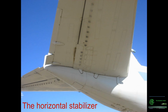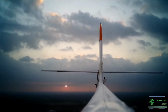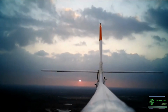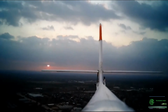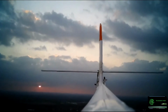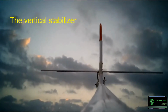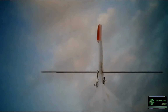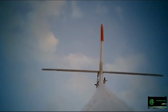The horizontal stabilizer. The horizontal stabilizer is used to maintain the aircraft in longitudinal balance, exerting a vertical force from the center of gravity, generating pitch moments. The vertical stabilizer. The vertical stabilizer is intended to reduce aerodynamic side slip and provide directional stability.